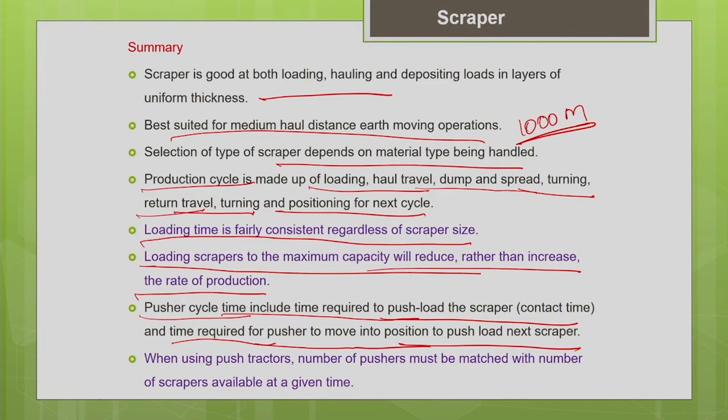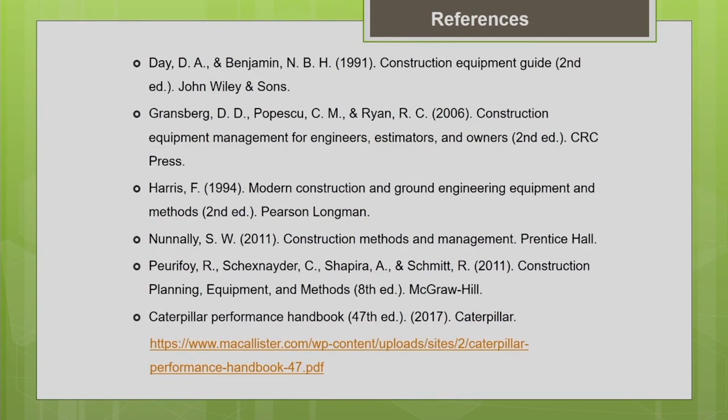When you are using the push tractors, we have to balance the number of scrapers and pushers. The number of pushers must be matched with the number of scrapers, so that we can minimize the waiting time of the scraper and the pusher. These are the textbooks which I have to refer for this part of the lecture.